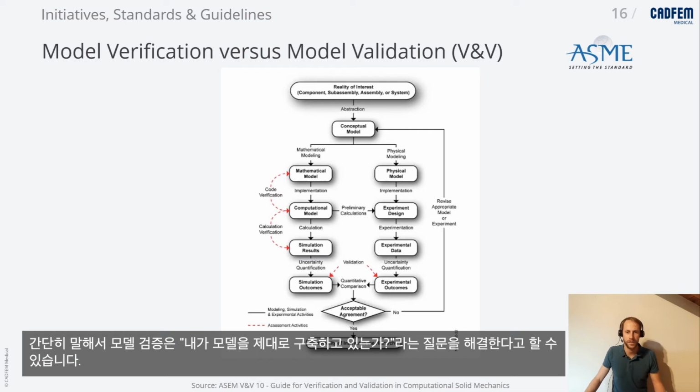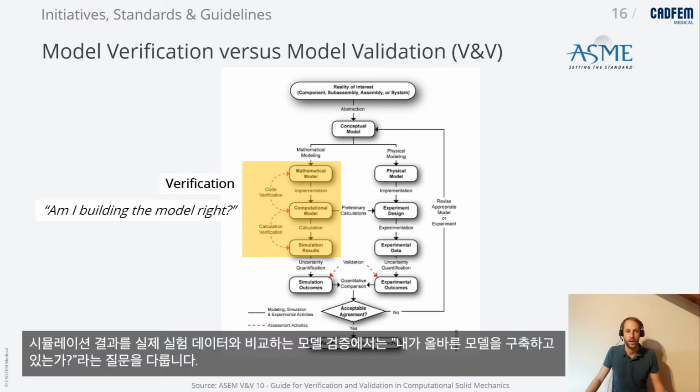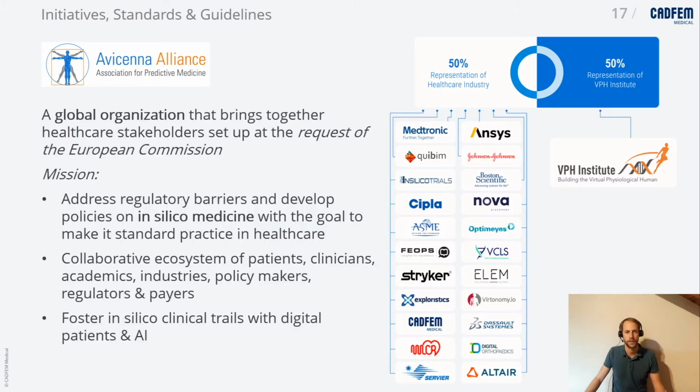In a nutshell, you can say that model verification addresses the question whether I'm building the model right, whereas model validation, where you actually compare simulation results with real experimental data, addresses the question, am I building the right model?